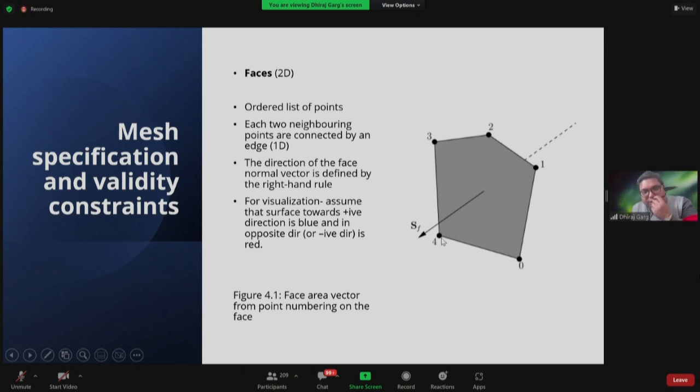This is how you write it in OpenFOAM, and it creates a face. Now remember this thing: instead of writing like this, let's say I change the order. Instead I write the order, let's say 0, 3, 2, 1, and then 4. So do you think, despite mentioning all the 5 points, it will create any real face? The answer is no, because it will change the formation of edges.